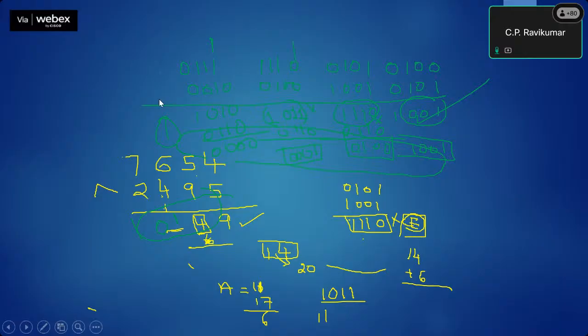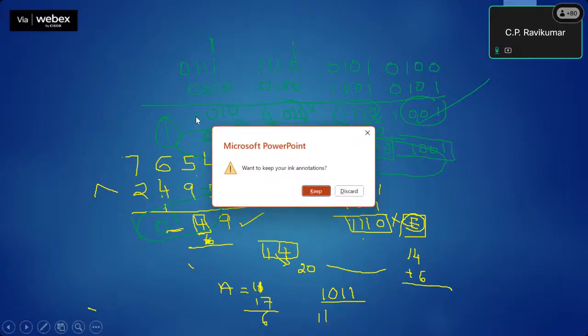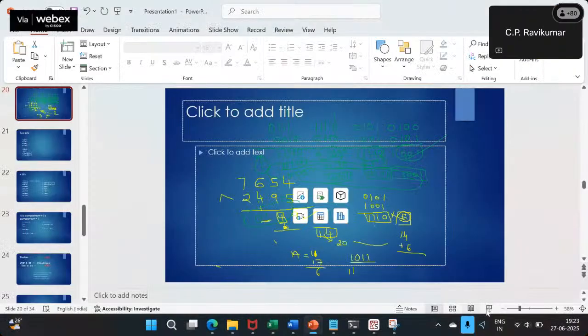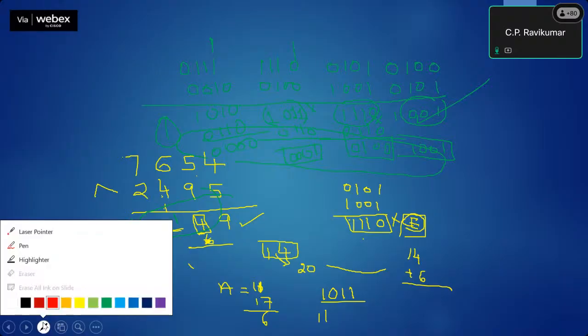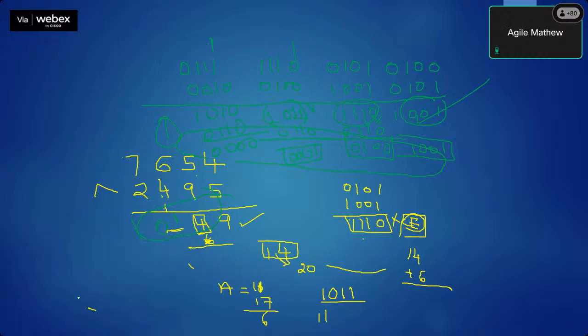So what is the condition for me to add 6? Under what conditions should I add 6? I should definitely add 6 if the resulting value is not BCD. If the resulting value is not BCD, I should add 6. Also, if the nibble generates a carry.